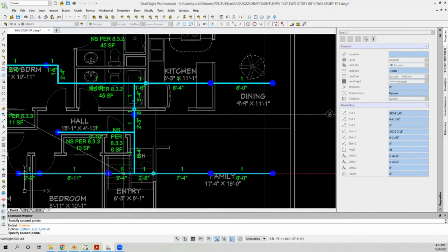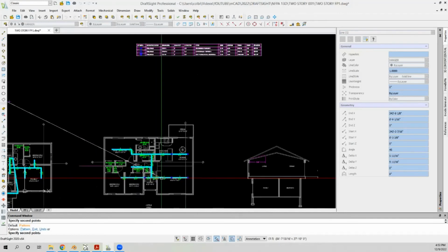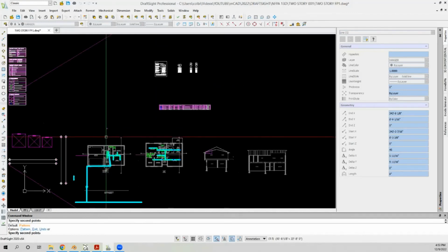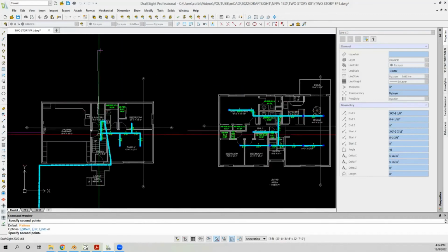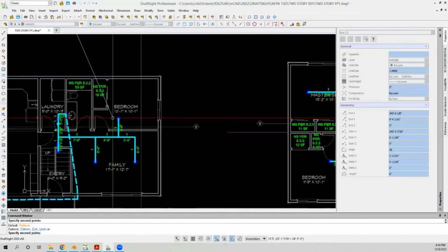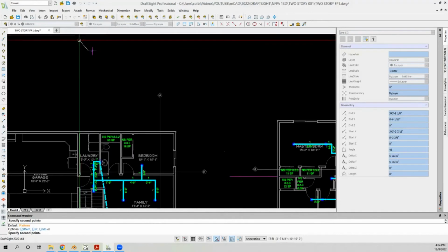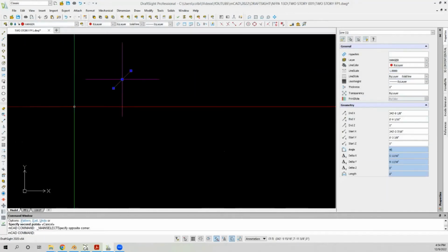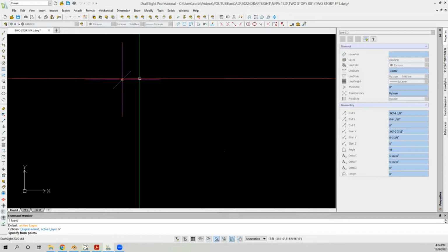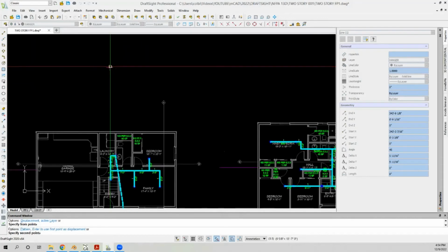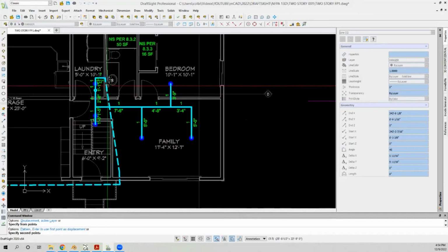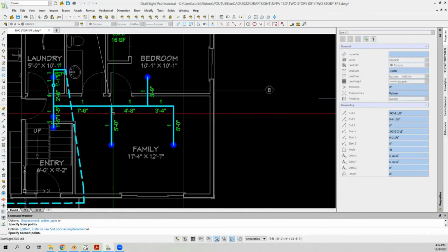So what we have done is, our standard for every job, no matter what it is, is we put hangers on it like it's 1-inch Schedule 40. Then we have a chart on the front that clarifies what the spacing of the hangers is, per NFPA 13D or 13, depending on what you're doing, or 13R.